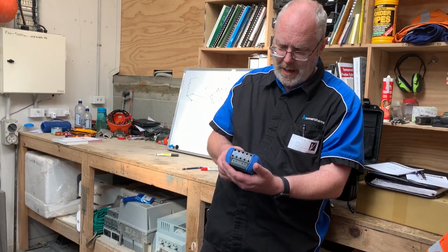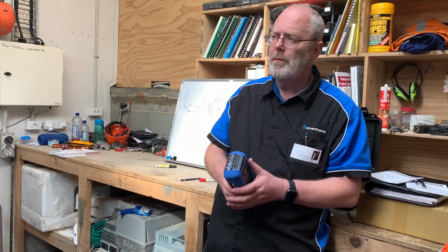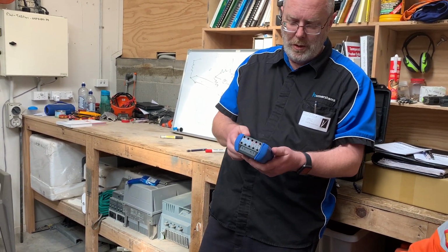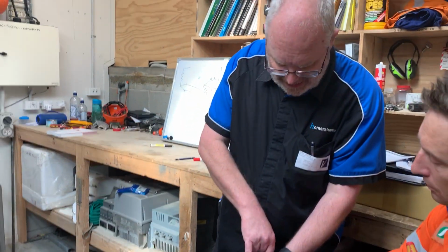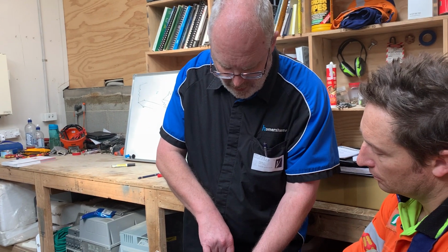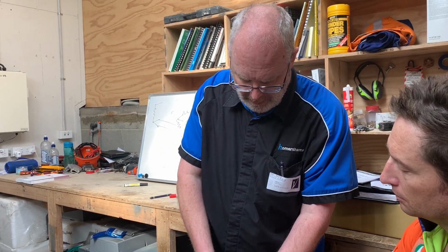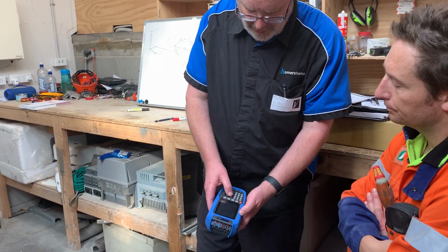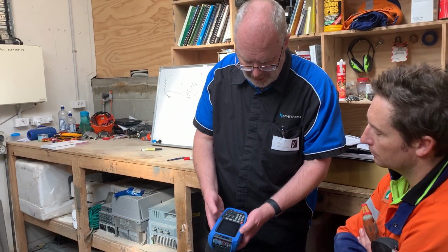Save as found. Any questions about that? No. You do the same thing for thermocouples. Everything we've talked about. There's a couple of buttons that don't do anything. On this model there is no HART. On this model there is no pressure. If it's a pressure model, there'll be a pressure port there. So that button will just beep annoyingly at you, as will that one. But any of these other functions, it will just source and measure.